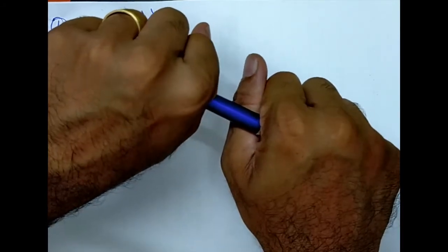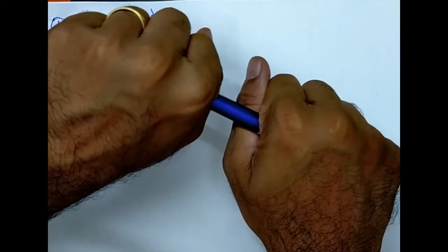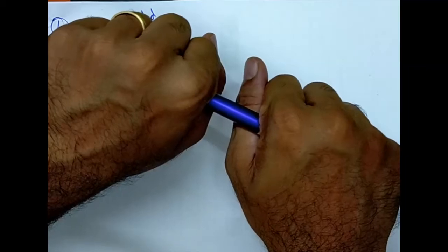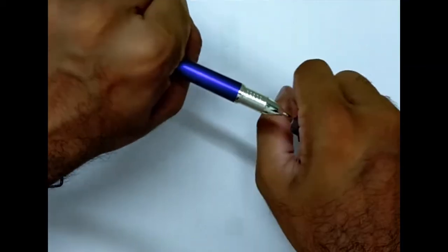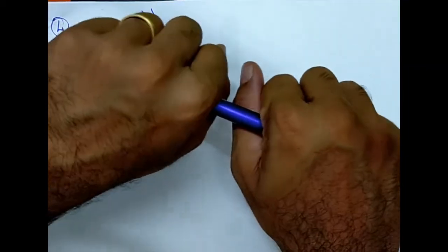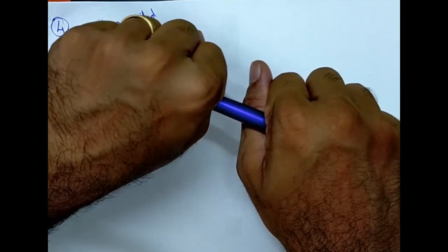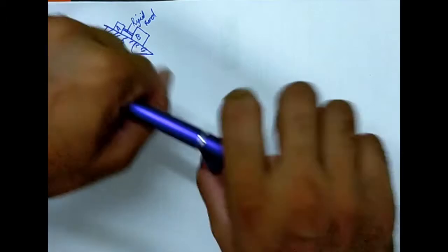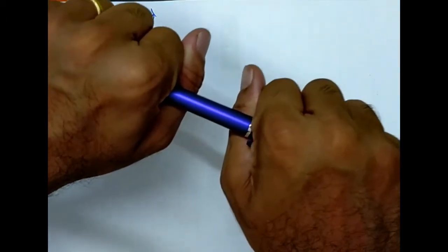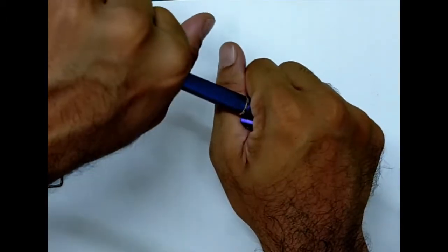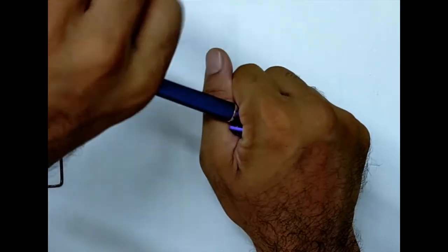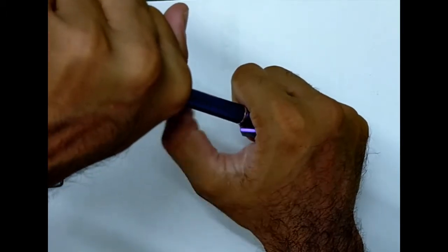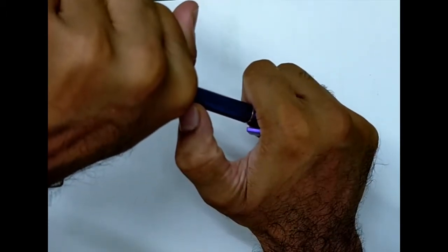So when we are using a pulley arrangement and a cable arrangement, because of the pulley, on the two sides of the pulley the objects will be moving apart, so they will be pulling it, so the cable will be under tension. Here it is the opposite case, one object is pushing the other object using the rod, so the rod will be under compression. So I'm assuming the value to be C.